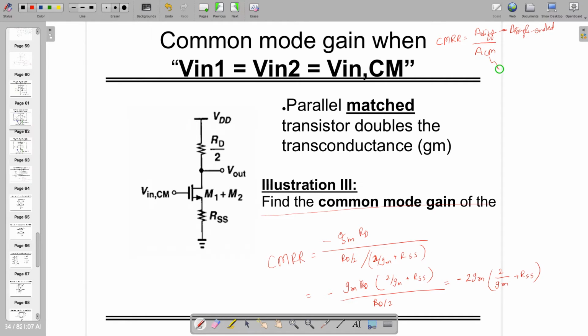In the case of common mode gain and differential gain, they are equal because you are giving differential as well as common mode at the same place, so both will be the same. So if both are the same, then CMRR equals 1 volt per volt, or you can say 0 dB. Sometimes people ask for this quick knowledge in interviews, so you can answer that.